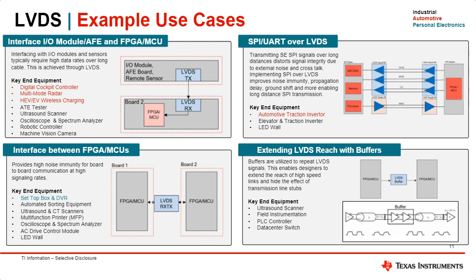One drawback and consideration to keep in mind while implementing LVDS over SPI is that the maximum clock frequency that you can support through SPI depends on the round trip propagation delay from host to the target device and back to the host.